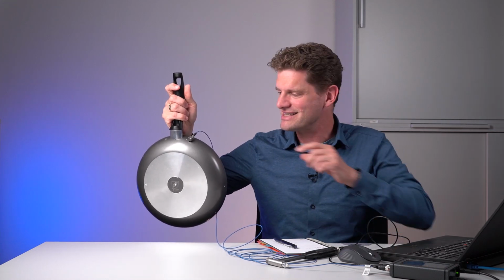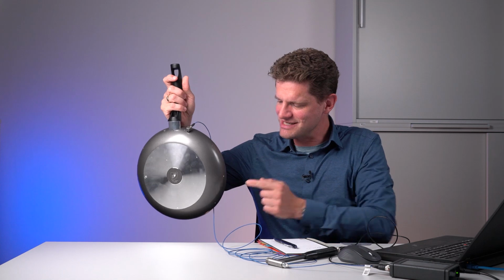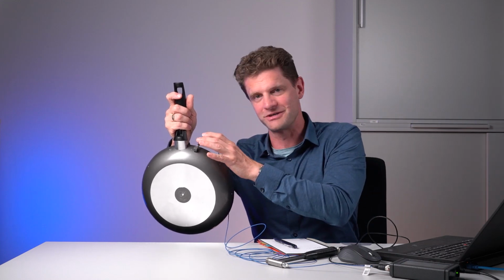We have a good idea how many eigenfrequencies are in this pan and where they are. But we cannot see them yet. I like to see how it's moved, what's happening at maybe 600 Hertz. And that's why it's quite clever to measure different FRFs from different points, always to the same reference, and then see the amplitude will change and the phase deviation will also change relative to the same reference point. And then we have an overall picture of what's happening in the pan at a certain frequency. So we just go on.